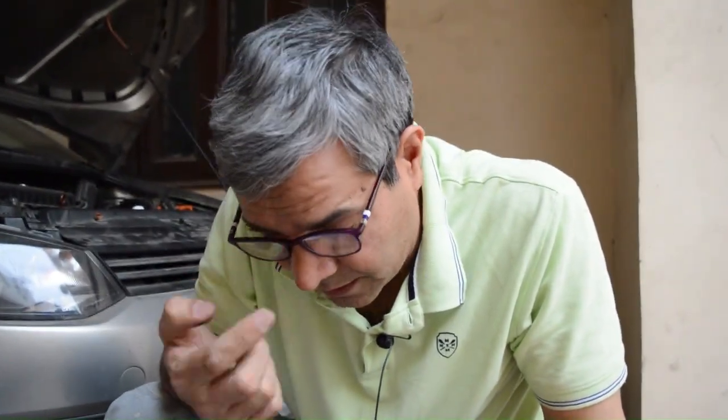get a voltage of 0.9 volts, and this message is then sent to the ECU, and then less fuel is injected into the system. On the other hand, if there is more oxygen in the exhaust gases, then it's considered a lean mixture, and in this case, of course, more fuel is added, and the voltage, if it is measured, would be 0.1 volts.